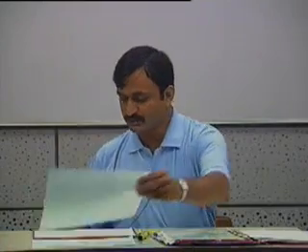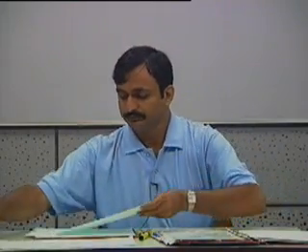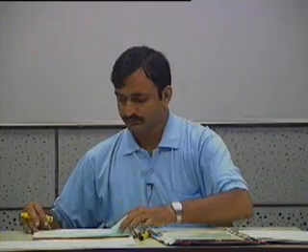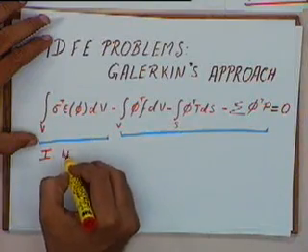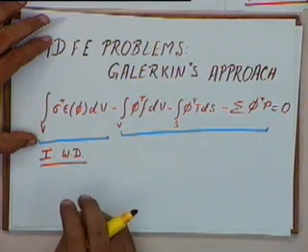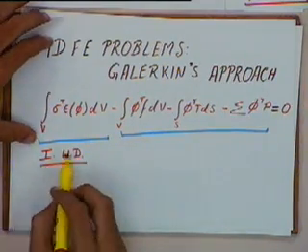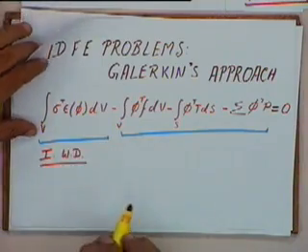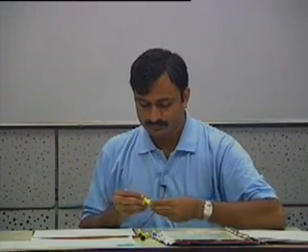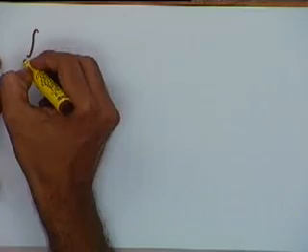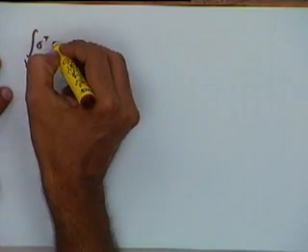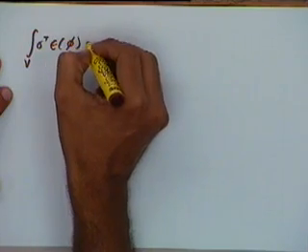If I take these two expressions, I can put them into the first term, that is this term, which corresponds to the internal work done, and if I expand this term, my first term here is the volume integral of sigma transpose epsilon of phi dV.